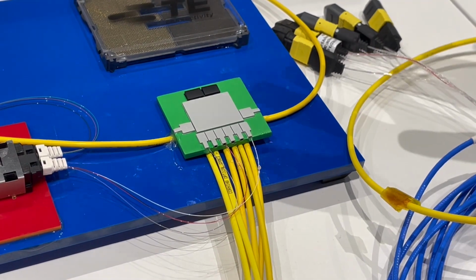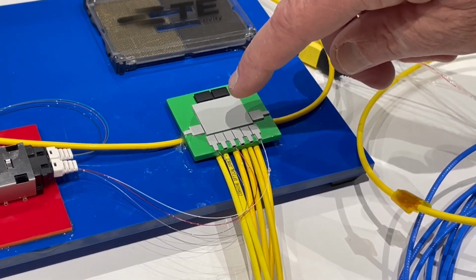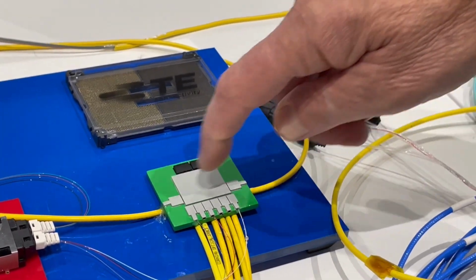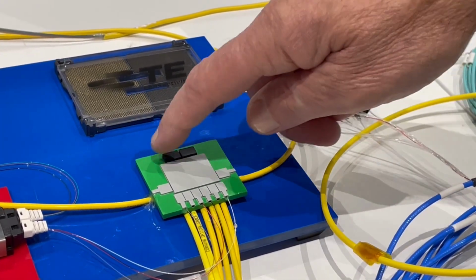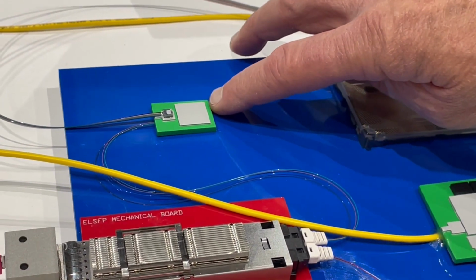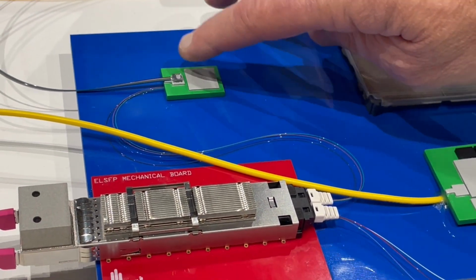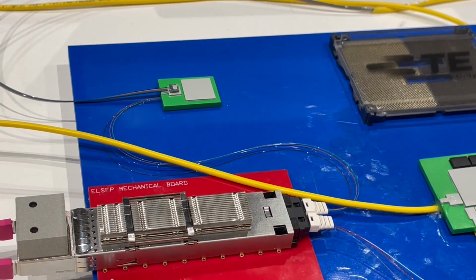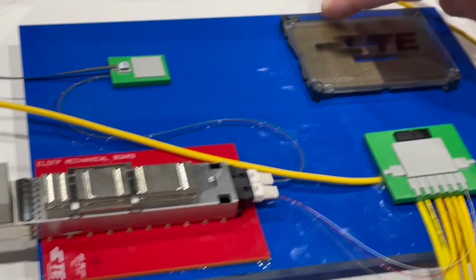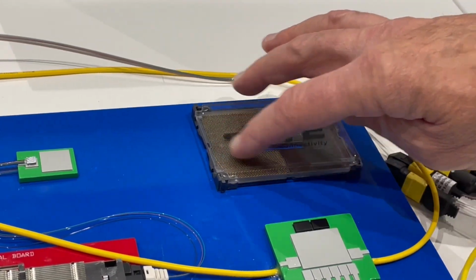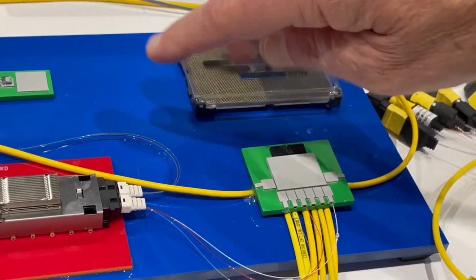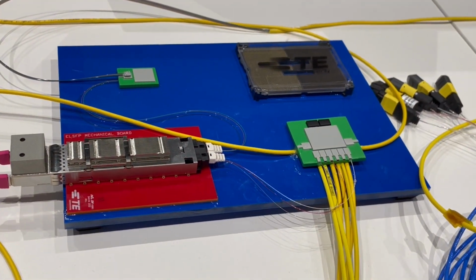And it shows you the size. So the bandwidth edge density here is about 1 T per millimeter. We also have some optical NICs on either side to reach out, and HBM memory in the back. Over here you see an example of a front-end NIC card, again co-package integrated with an optical engine on the side and the ASIC there. And then this is just for reference as a CPU socket, as we'd have today. And you can see the optical engine powered up by external laser source.